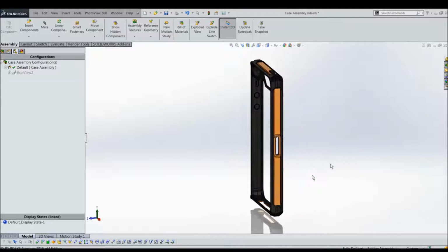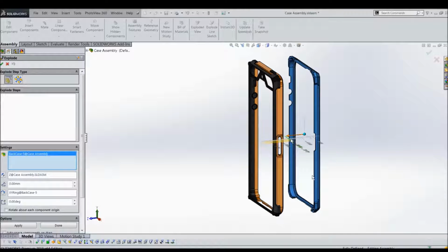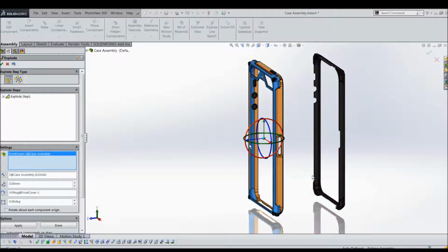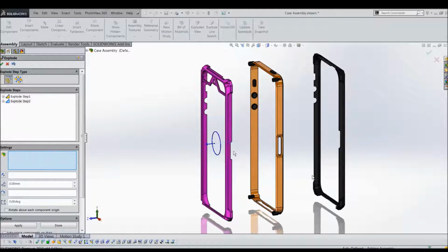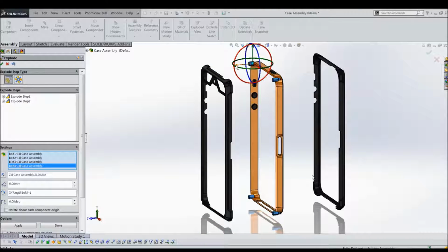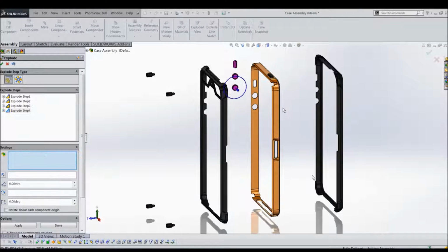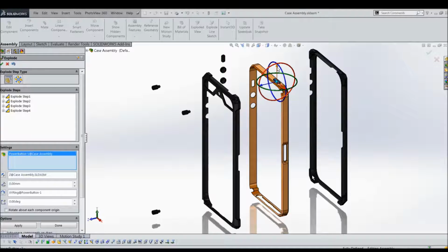Now the assembly is completed, and we could create some exploded views of the assembly for better instruction. In SOLIDWORKS, we could easily create an exploded view by dragging the parts or assemblies to the desired location. It can be either linearly or radially dragged in the 3D space. After creating the exploded configuration, the explosion process could even be animated and saved as a short video.